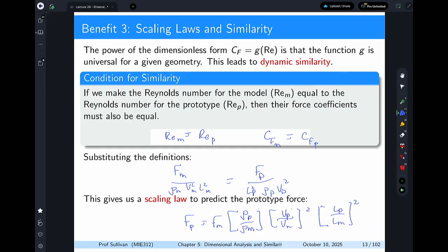So even if I match everything else up, and say for some remarkable reason I did match up velocities, a 10-times change in length from the prototype to the model is a significant change in terms of forces. So it's a factor of 100, just for 10. And that's a pretty normal scaling.